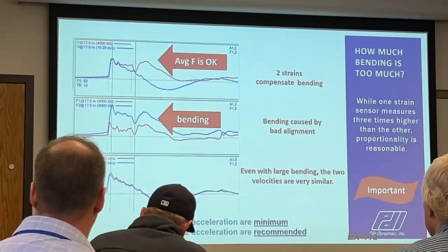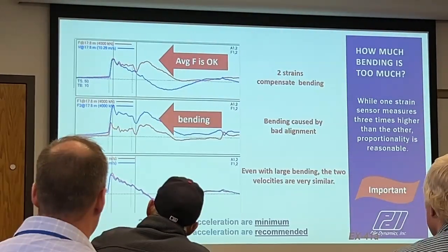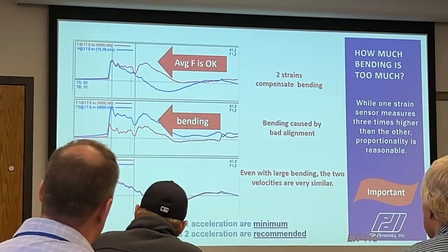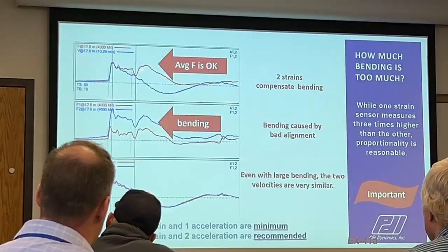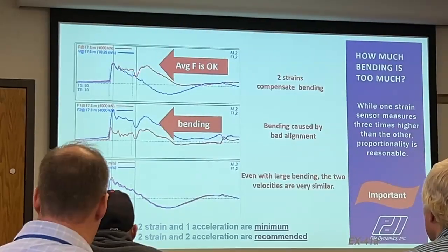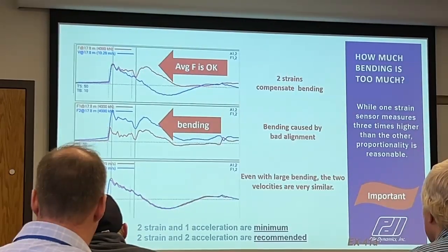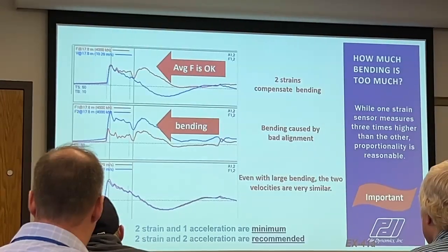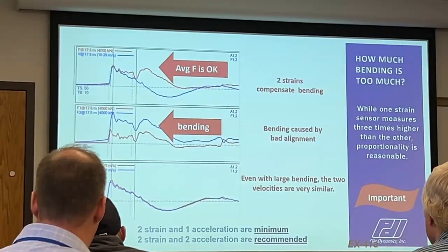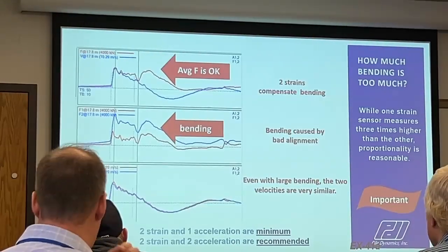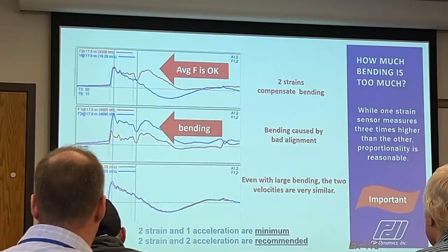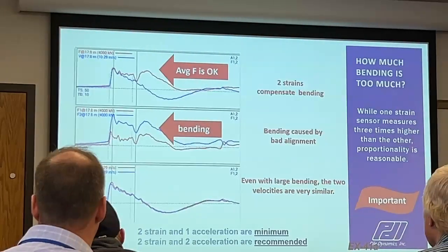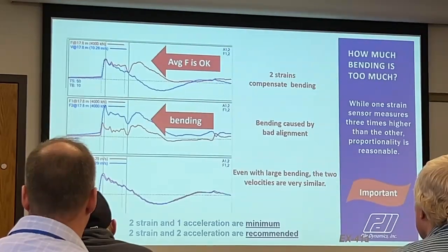Is this proportional? Yes, it is proportional. Is there any shaft resistance? Yes. Our force trends towards 0, our velocity increases, and then we get a big reflection in force. That tells us that it's not a fixed end, but it's pushing into the soil, and then the soil is really starting to push back. So this is probably more consistent with something like a dense sand.